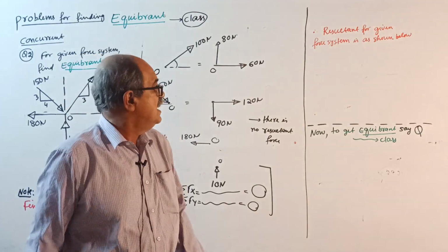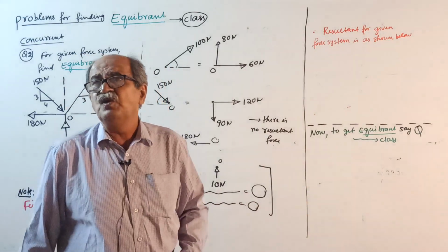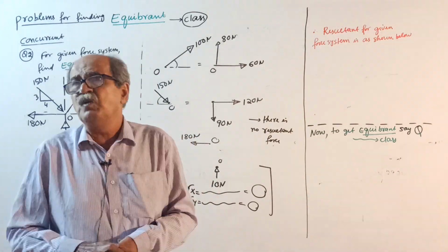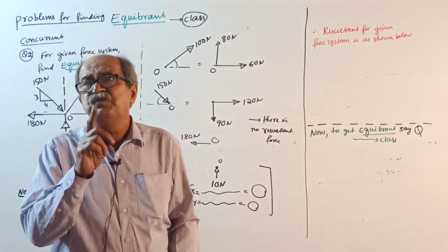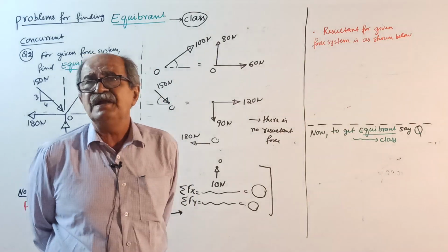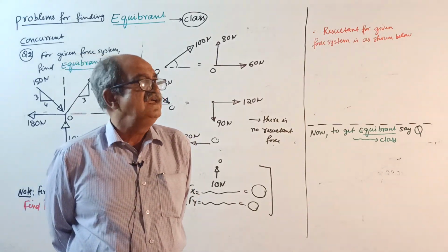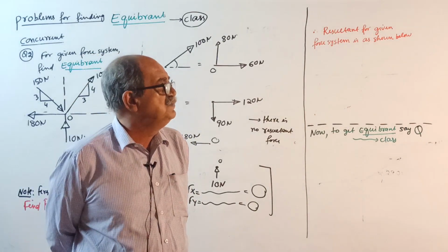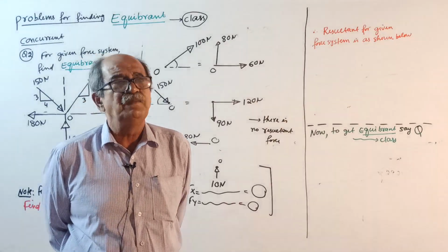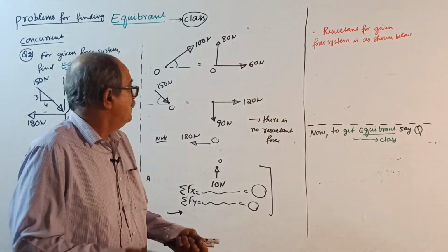So, as soon as you get resultant force 0, find the algebraic sum of moments. This is only when the resultant force becomes 0. To check whether the resultant exists in the form of a couple, find the algebraic sum of moments of all the forces about any point.